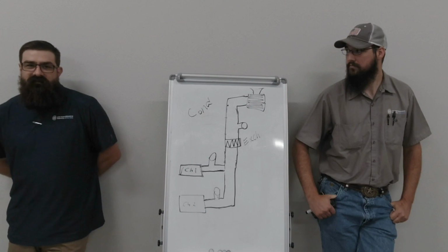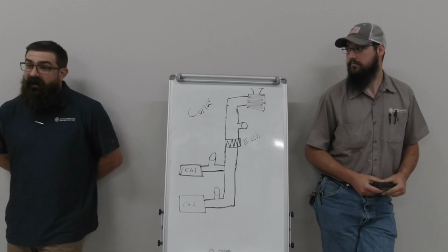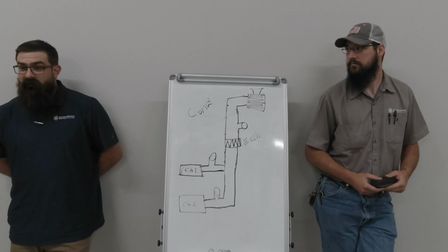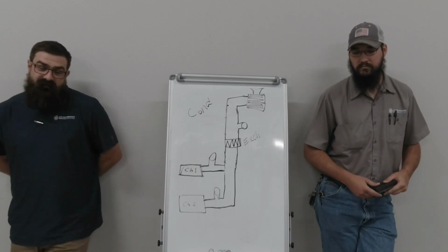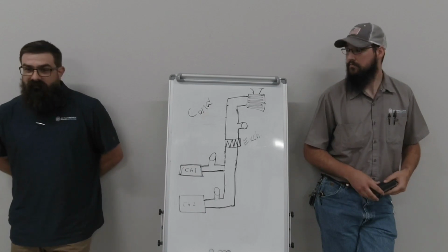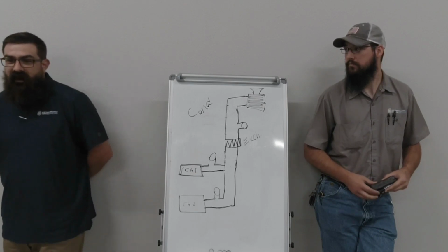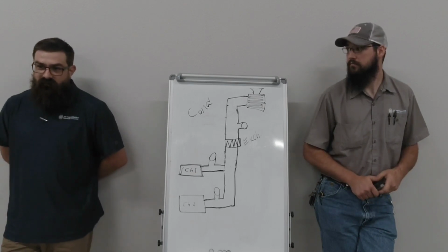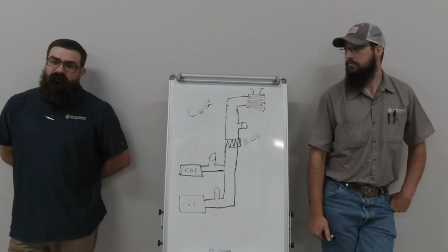We talk about heat exchangers, so like there's ice storage, chillers, right? A chiller can create ice, really, really cold water, and then store it as ice. And then you use your ice as basically a heat exchanger. You pass water over the ice to cool it and make chilled water instead of running your chiller all day. So you can run your chiller at night, create ice, and store it, and then during the day, you use that as stored cooling.